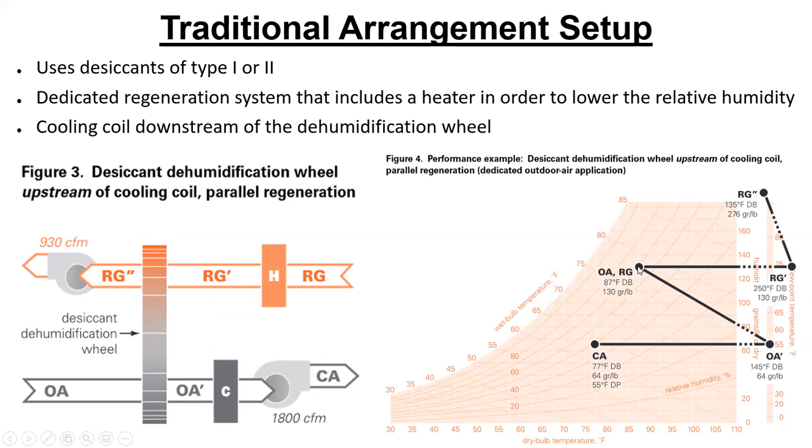Okay, so this is outside air. This is where both of these are starting. So this is the regeneration air. Well, we start with outside air for regeneration air. And then over here, this is what we're going to use to blow into the space for ventilation. Well, it comes from outside too. Okay, so they're both going to start from the same air coming from outside. It's just we're pulling some for regen, and some other for actually ventilation air.